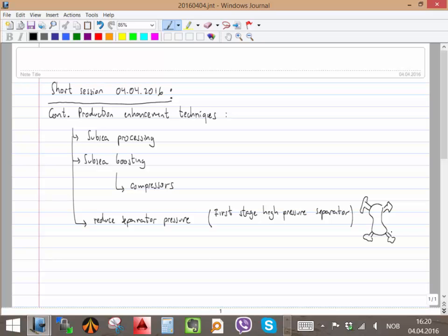For example, Snow White, they are going to lower the separator pressure, I think from 2020, just as a measure to obtain more from the reservoir, to obtain more production. But that's not something that is typically done unless you don't have many downstream processes that depend on that, or you are planning to compensate somehow, let's say by putting some boosting equipment downstream to increase pressure. But that's not something that is typically done.